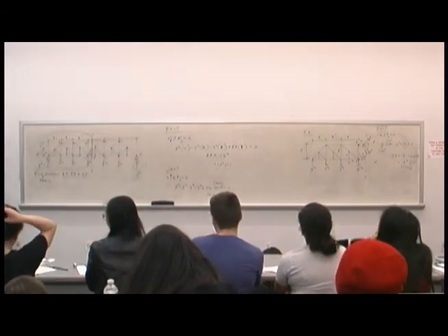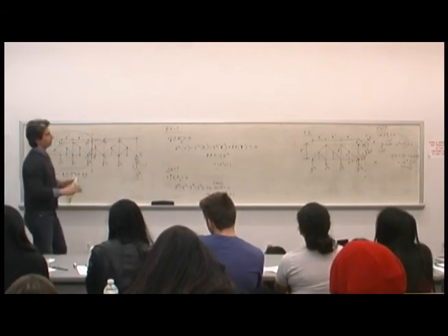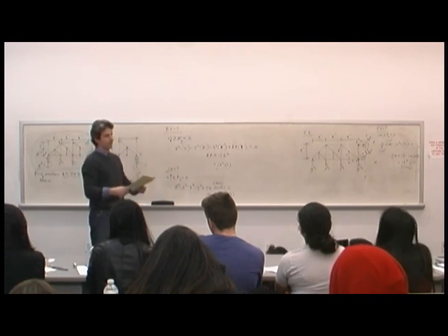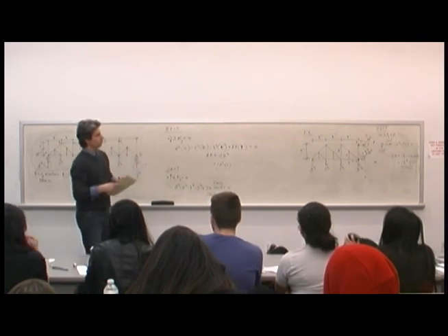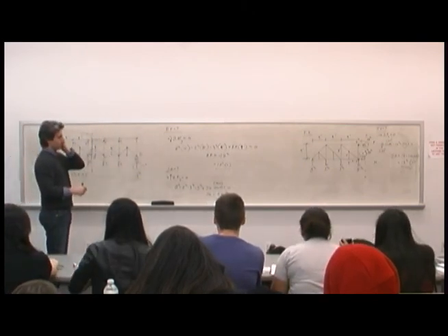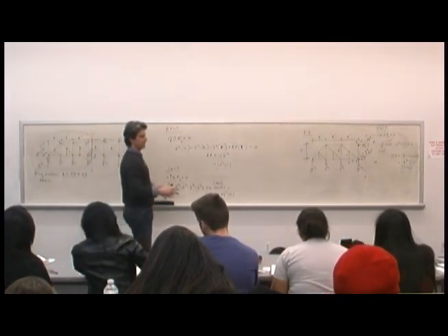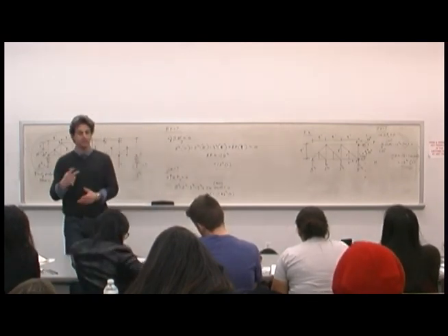Okay. So we need to practice this method of joints, method of sections, all right? And we're going to go over it in the seminar. So don't let it trip you up. It's really the same exact thing that we've been doing. Everything we're doing is equilibrium, and everything we're doing are the three equations of statics. Sum of the forces vertical, sum of the forces horizontal, and then the moments, no matter what we're doing.